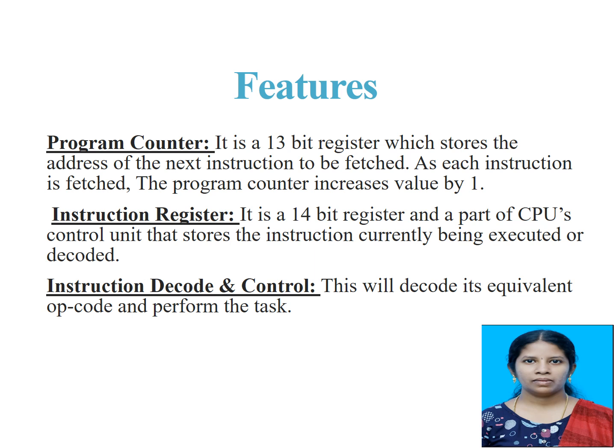The PIC microcontroller has the program counter, which is a 13-bit register. Program counter is a register that stores the address of the next instruction to be executed. The program counter is incremented after each instruction is completed. It also performs sequential execution. The program counter keeps track of the program sequence, allowing the CPU to fetch the instruction from memory in a step-by-step manner. After each instruction, the program counter is incremented to the next instruction address.